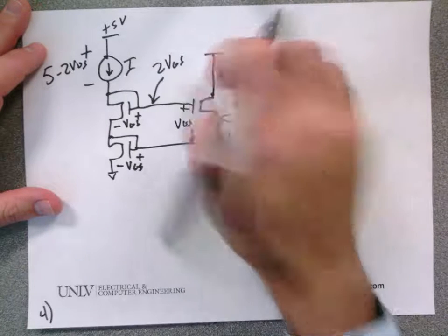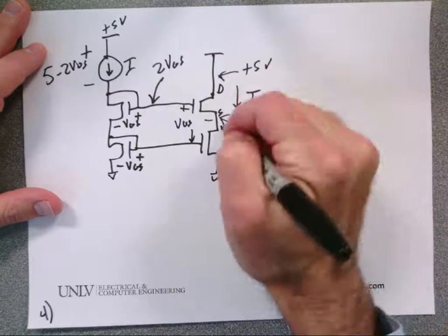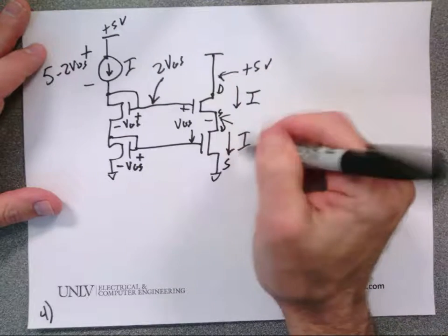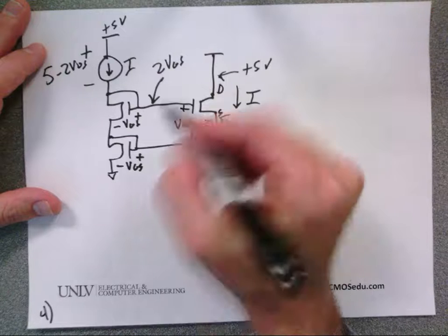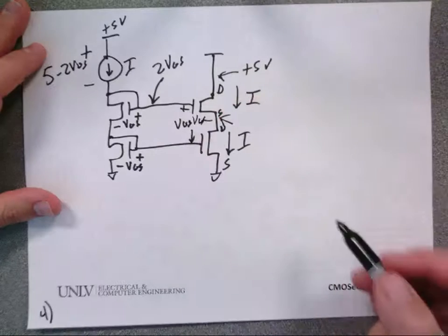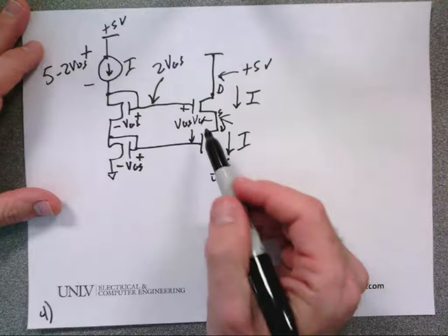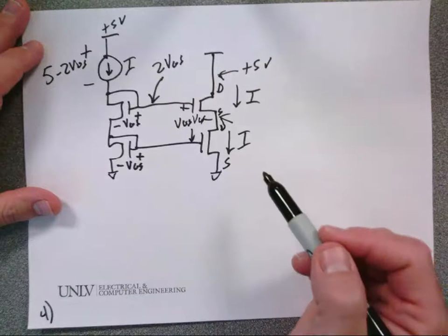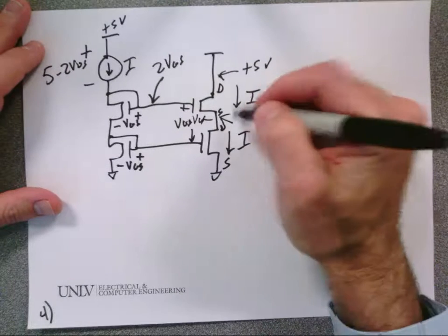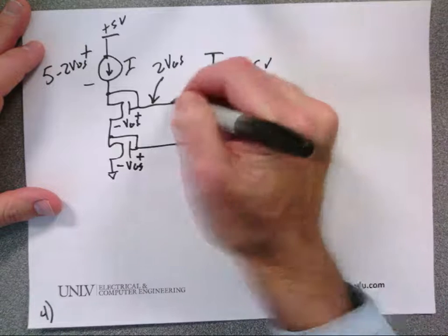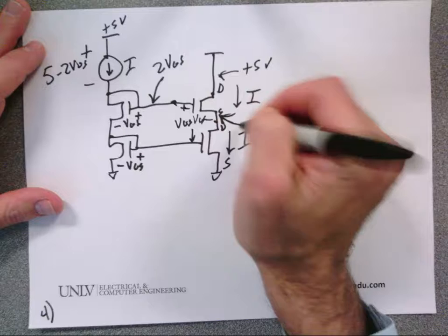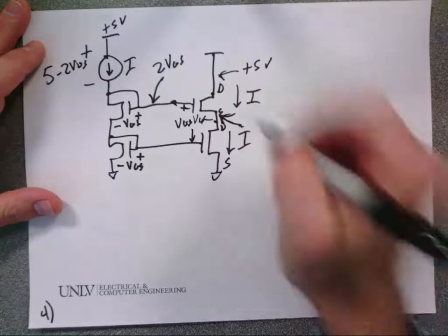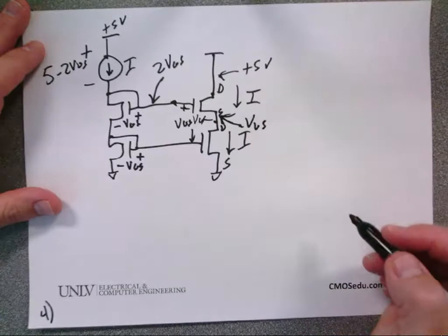It flows from the drain to the source, to the drain to the source. The current here is I, the current here is I. So what does the voltage here have to be? VGS. How do I know that? That's the amount I turn the valve on to get the current to flow. So then I ask, all right, what's this potential here? I got 2 VGS here and a VGS drop here. Second floor, then I go down 1 floor. What's the voltage there? VGS, 1 floor. Does everybody see that?